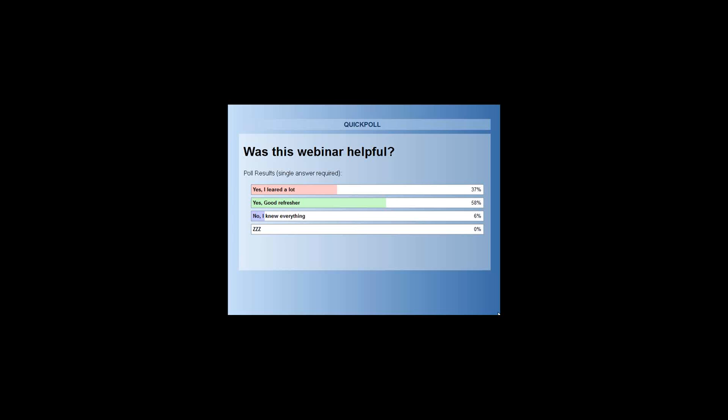Yeah, a good place to search for things like that as well is the crash modification factor countermeasure clearinghouse. Right. If you Google the CMF clearinghouse and search for rear-end crash reduction at signalized intersections, you may get some quantitative information, the percentage expected reduction for different types of countermeasures.